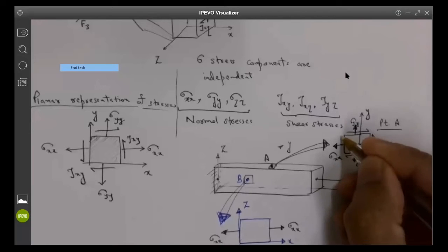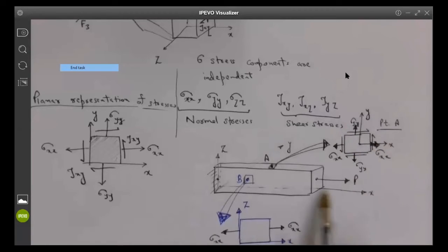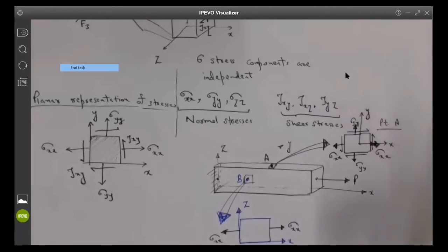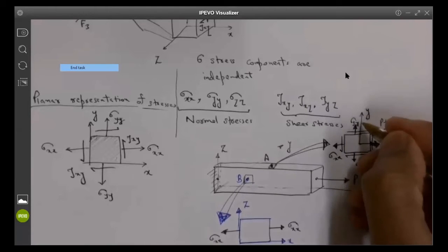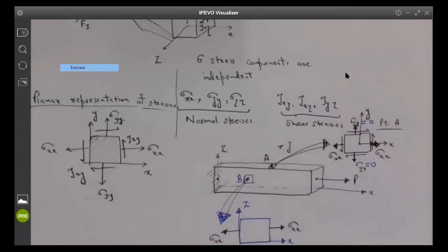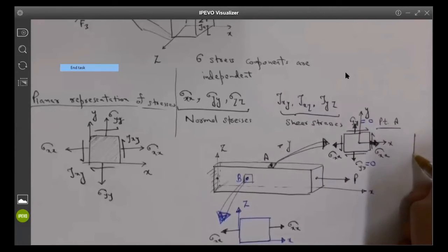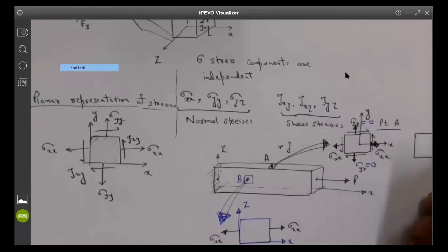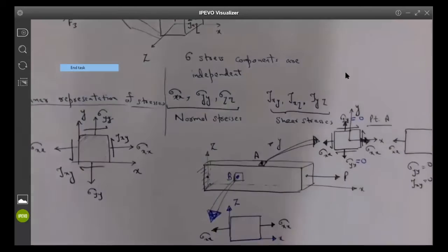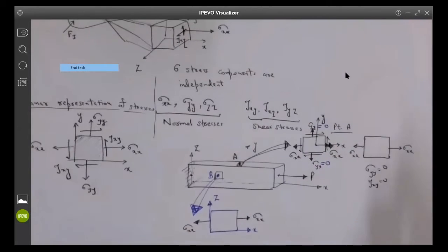Now this is for the generic case. Generic case means generic loading case. For our uniaxial load case, I know only sigma xx is present. These components are zeros because they are not present in the material at this point. Neither sigma yy is present, nor tau xy. Are you seeing what I'm saying? So here I only get sigma xx. Sigma yy equals 0 and tau xy equals 0. So that's why I'm not representing it. Is everybody getting it so far?